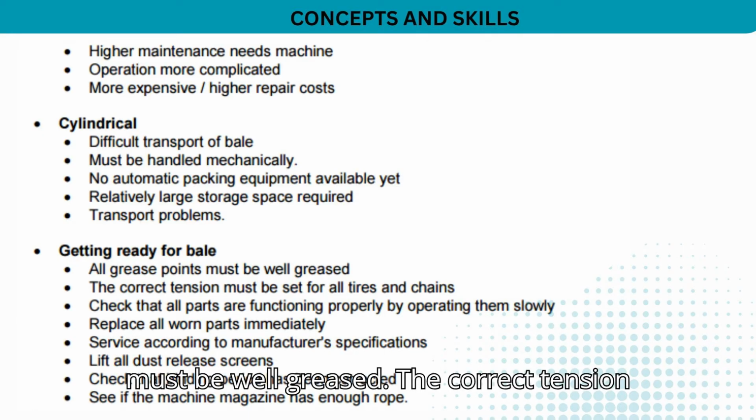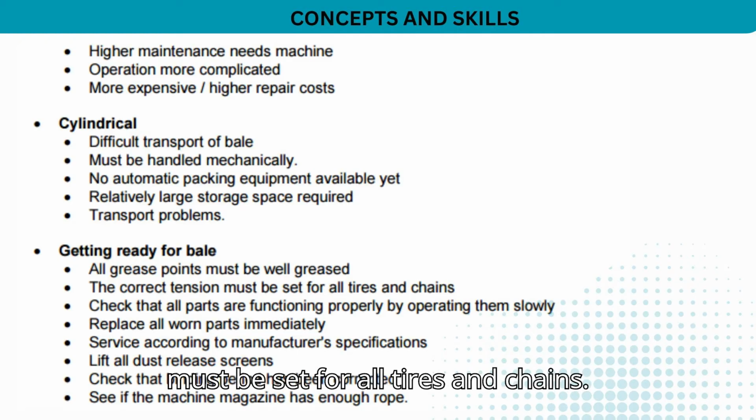Getting ready for baling. All grease points must be well greased. The correct tension must be set for all tires and chains. Check that all parts are functioning properly by operating them slowly. Replace all worn parts immediately. Service according to manufacturer specifications.